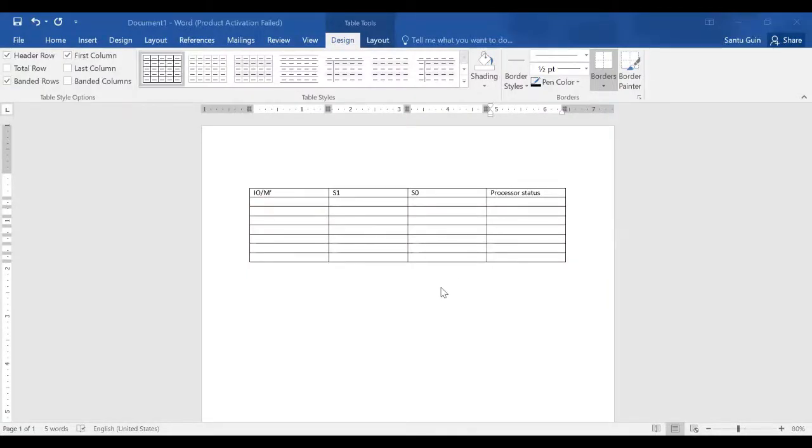So, processor status signals: what will be the status of each one? If you have pen and paper with you, write it down the way I have written it over here. Is it visible? Yes, sir. Okay. If IO/M bar is 0, S1 is 0 and S0 is 0, then the operation status is the halt state.